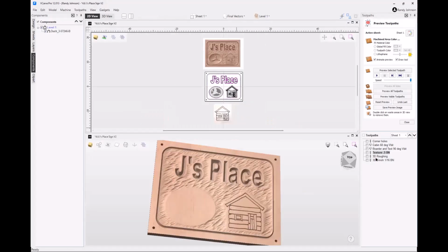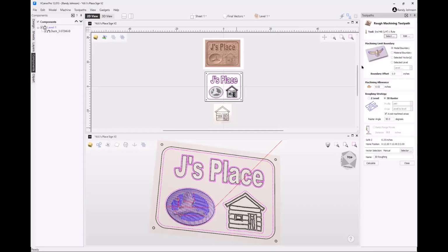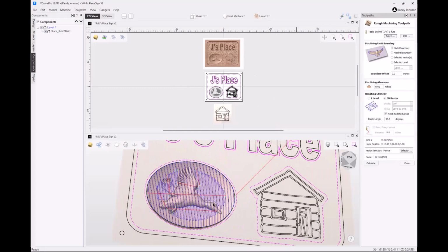So finally, we're going to do the 3D toolpath for the roughing for the model. I'm going to open that up and show you a difference. Last time in the upper right here, we had model boundary set up, but our whole project was the model last time. Now it's just this part of it that's the model. And so when model boundary is set up, in this case, it's going to restrict the carving just to where the model is. So that's one of the advantages of doing it this way: I only have carving in that part of it, so I don't need to 3D carve the rest of my project. And so that's set up like that.